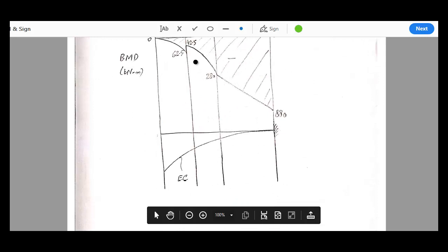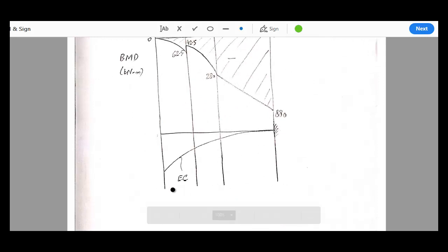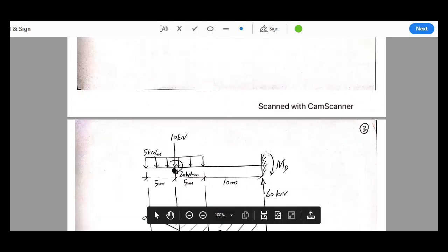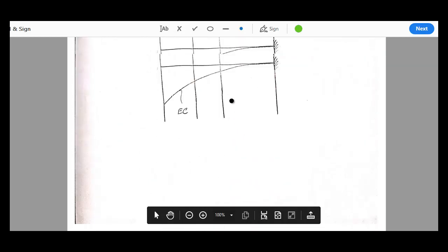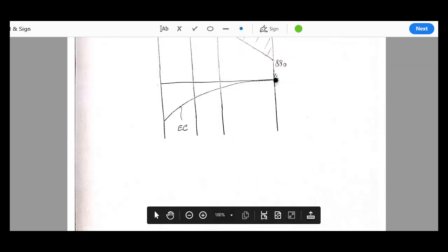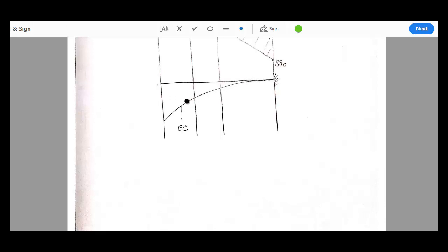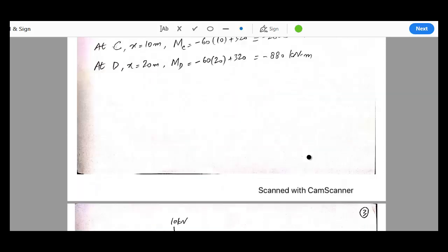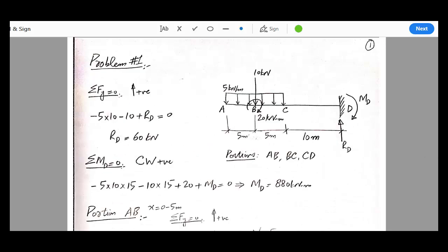So this is the bending moment diagram. The entire bending moment diagram is negative. So the elastic curve, because this diagram was quite complicated, I have drawn it here. This is the beam, and the entire bending moment diagram is hogging. The beam is hogging down. So this completes the solution of this problem. I think with this we can stop recording here. Thank you very much.